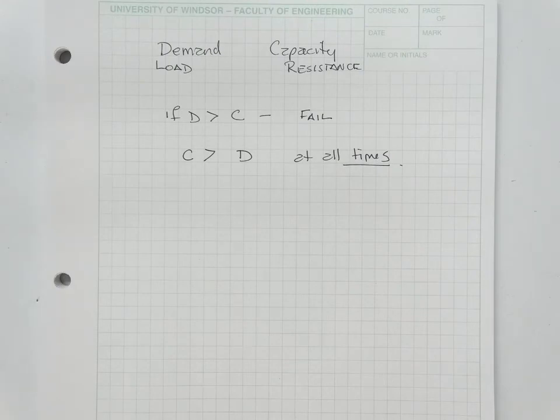If you were to walk into a building and as you walked along it, the building kind of bounced, how would you feel? Like, get that out of here, right? Like every house in Menominee. Very old wood, right? Fatigue gets into wood as well. Have you ever been on a bridge, stopped traffic, and felt it move? Because people don't walk on bridges. We don't make bridges as stiff as we make buildings, because we don't mind that it moves a little bit. So it can fail in stiffness.